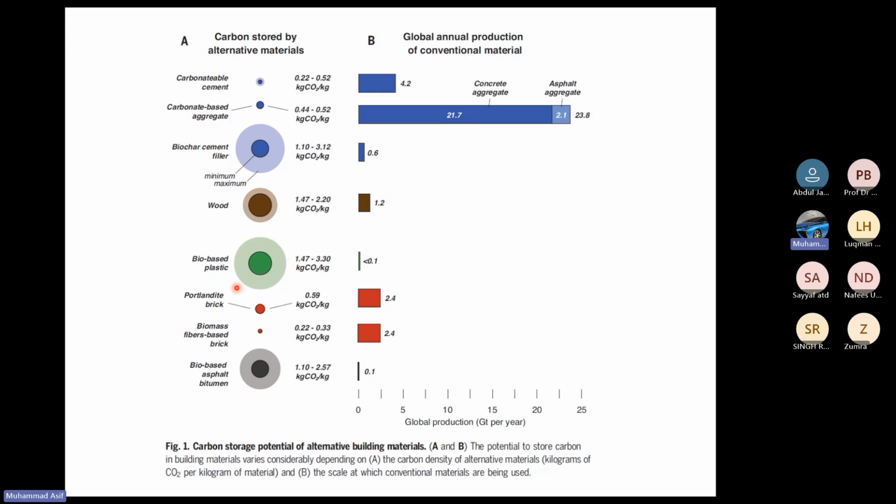So what is the result? After this long discussion, the summary may be this: for bricks, we have clay, and we have cement, Portland cement, which is produced through the mineral calcination process that emits carbon dioxide. If we do not use Portland cement, we can cut off the CO2 emission from cement preparation, and the other materials, biomass and renewable energy based materials, can be used there. It will cut off the 2 to 5% of CO2 emission that comes from the cement industry, and then it can capture carbon dioxide from the environment to help us get overall carbon neutrality.